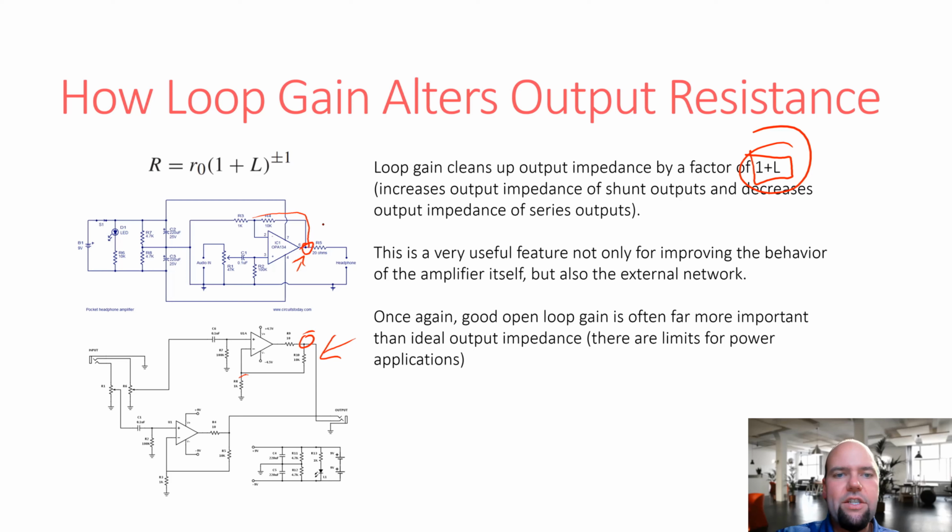And then your headphones connect here and the headphones are in series with a 20 ohm resistor. So this circuit is literally the same as just putting your headphones in series with a 20 ohm resistor. We're not correcting the signal on the other side of that 20 ohm resistor. But actually, this is probably okay too.